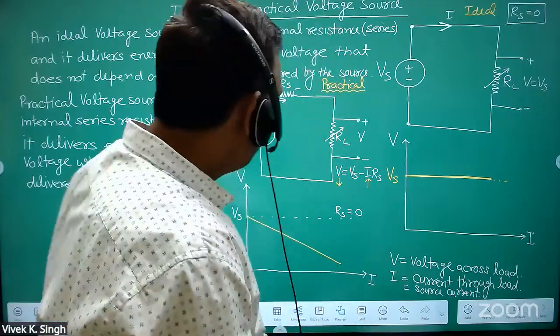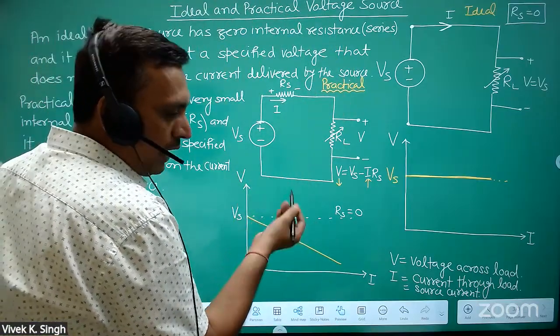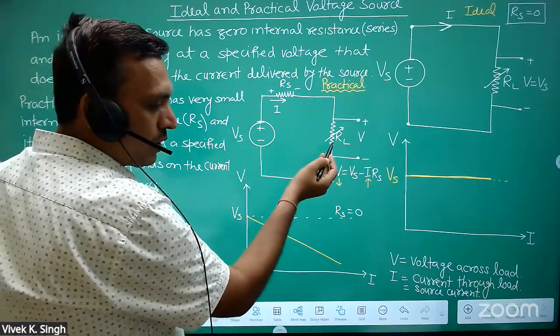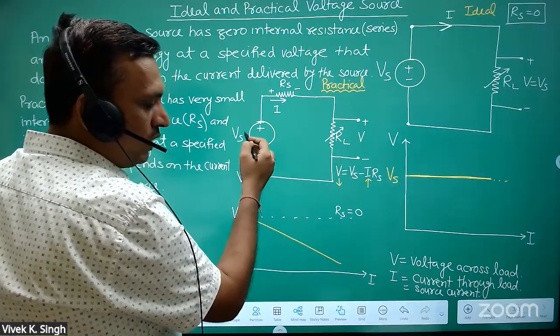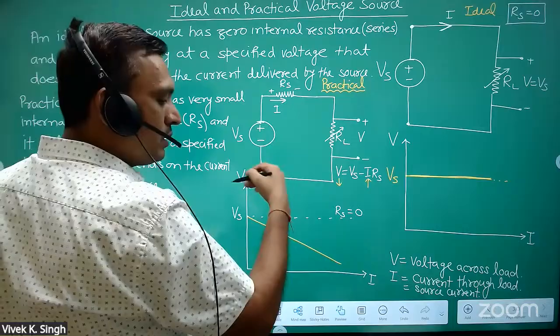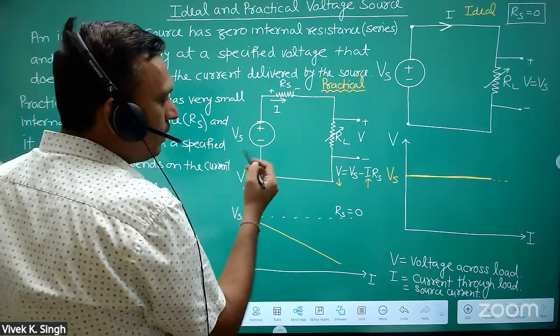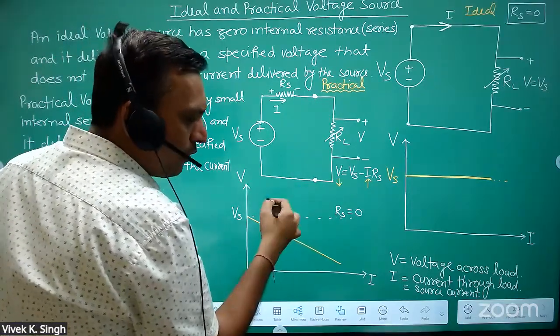So we will discuss this problem, which is also called the loading effect, because when you are connecting some voltage source across a load, you are not getting this voltage close to Vs. This drop will be across its source resistance itself. So we have to avoid the loading effect. How should you avoid it?